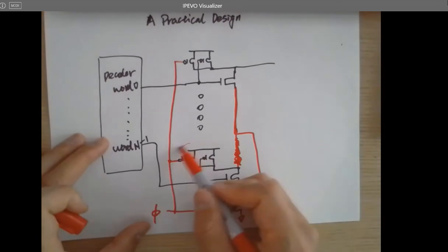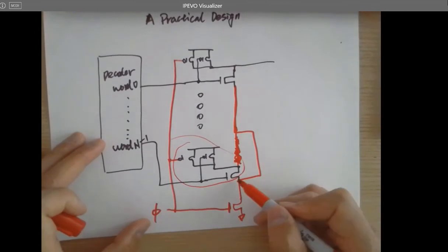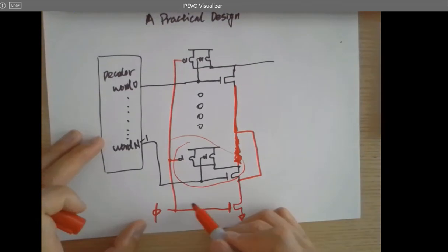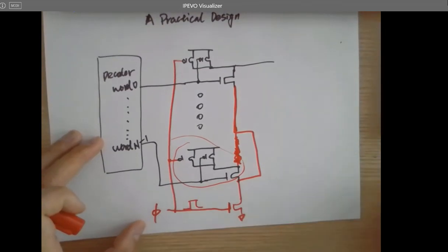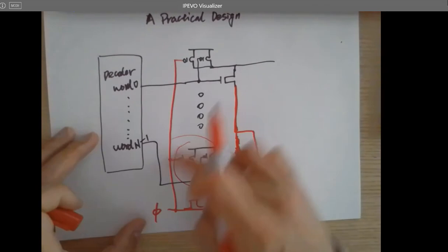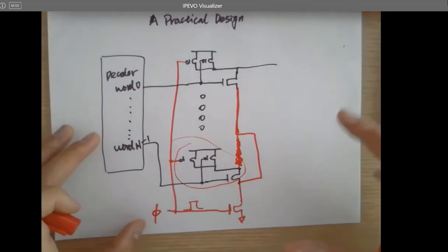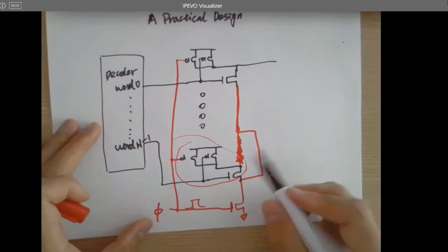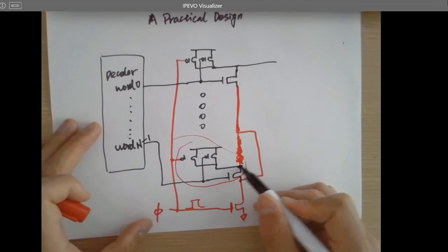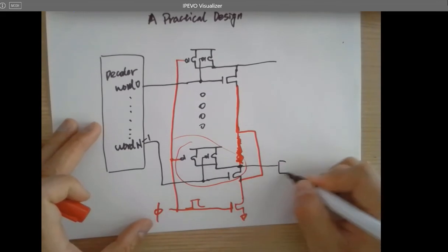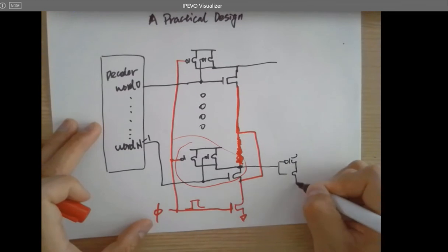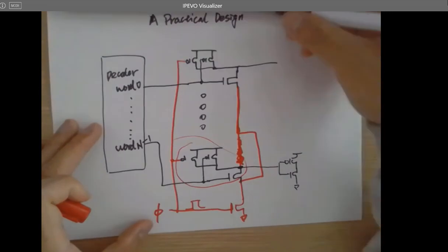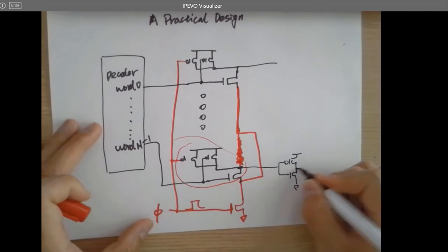So this one is independent, but only the sources are being shorted to this clocked NMOS. So whenever this is on, for example, this is on, and let's just look at this one. It's just repeating. It's the same for the other ones. If I just look at the bottom one, and for example you invert it, here's the drain, that's the output. This will be connected to another inverter as well.